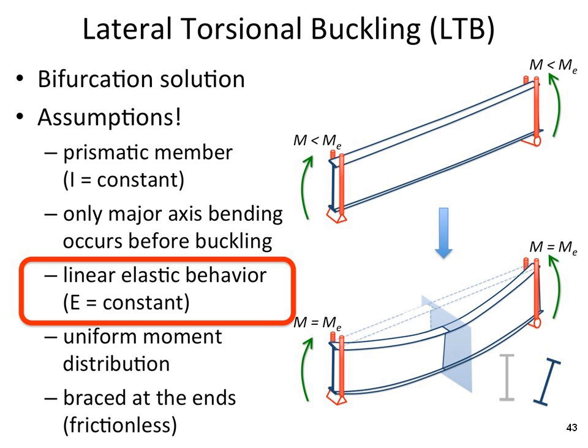The only other thing I'd say about that warping term is you've got to watch, I believe sometimes up at the top of the table it says multiplied by 10 to the 6th or something like that. The warping coefficient does get very large, but those numbers are provided for you for all of our standard shapes. Okay, and we have a couple more.